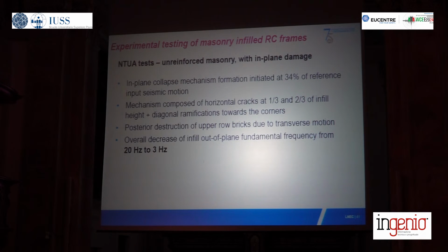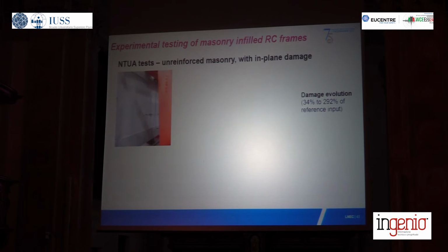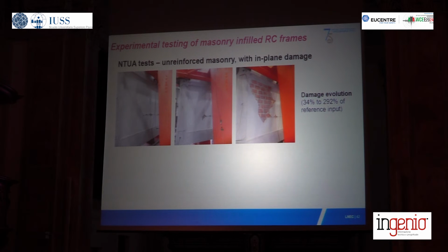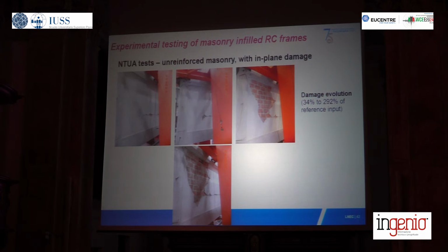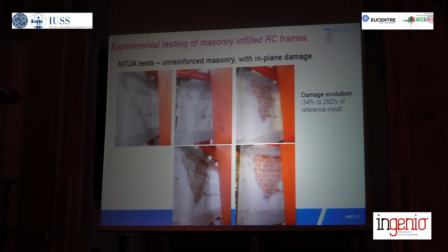In terms of the out-of-plane fundamental frequency that we were measuring, we went from the beginning to the end of the test from 20 hertz to 3 hertz, so a huge decrease of the stiffness. And so you see here the damage evolution throughout the different stages of the test.